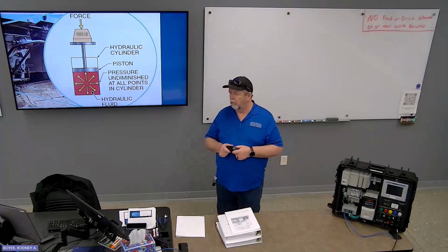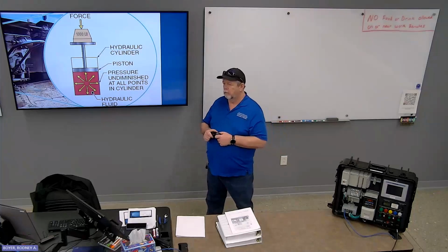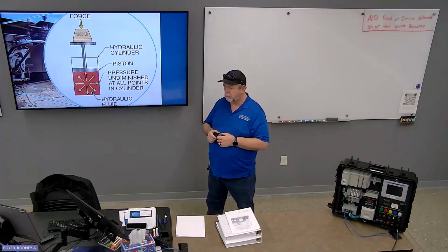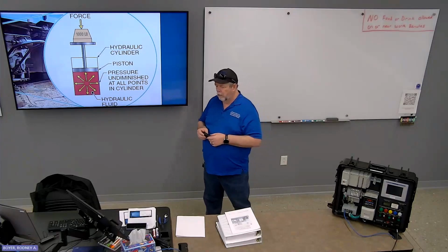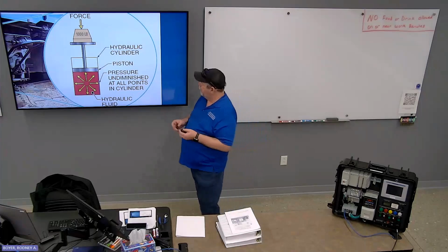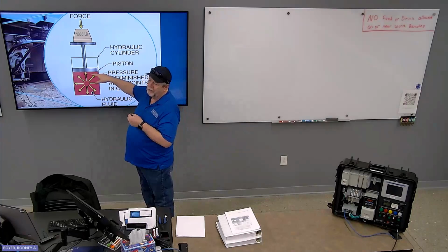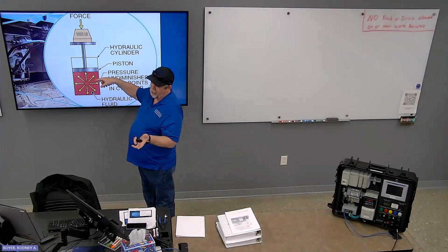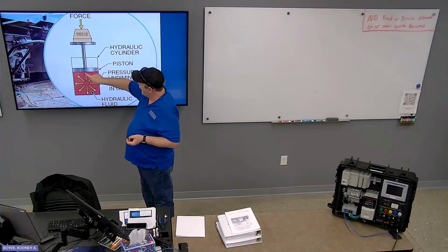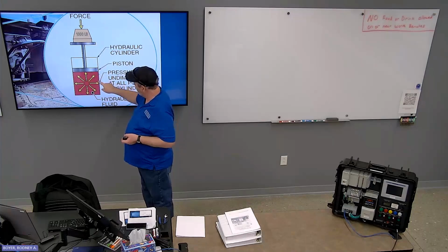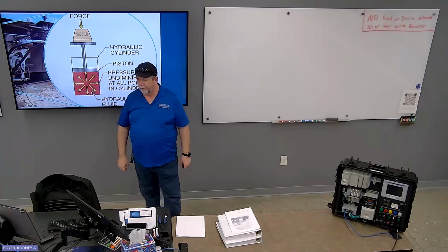Is that saying you have 1,000 pounds of pressure at any point on the cylinder? Yeah. That's why the multiple arrows are going in all directions. That's that undiminished part. Yeah. Got it. So you would measure, well, it depends on surface area here, because force is pressure times area. But you would measure the same pressure there as you would there, anywhere. Okay.